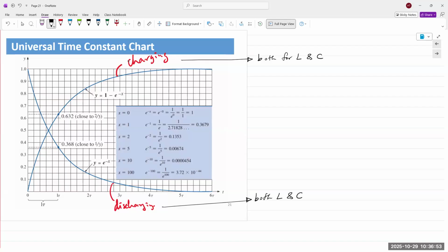So based on the frequency of the incoming signals, the capacitor and inductor filter out or bypass high and low frequencies, and allow low frequencies to go to the bigger speaker and high frequencies to go to the smaller speaker. So those are the real life applications for capacitors and inductors.